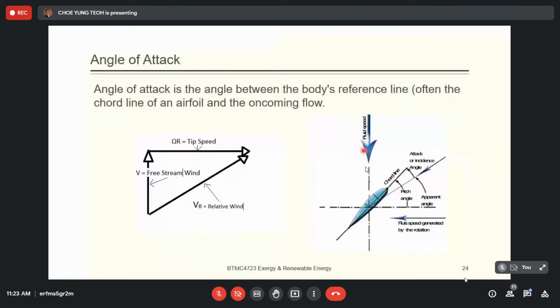How to do that? If you look here, let's say my rotational turbine blade speed is consistent, then this fluid speed is able to change the angle of attack. So if I consider the change between these two speeds, I'm able to control the angle of attack. So I adjust the angle properly, and then fix it and install. And there's no other control after this. So it means that the turbine blade is fixed there.